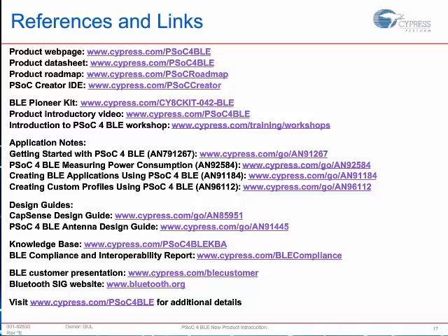So a couple of things. If you use the PRoC module, which is pre-certified by the FCC for its wireless portion, and you simply plug that into your system, you don't have to recertify the wireless side. But as I mentioned earlier, in most cases you may still have to recertify your entire system as a whole, because it may be doing other things outside of the realm of the PRoC module. At that point, you will need to go through your own independent FCC certification, depending on what geographies you're trying to sell the product in. But you can go back and reference Cypress's pre-certification on the FCC part for the wireless aspect of the design. So when using the pre-certified module, life becomes a lot easier with the FCC.